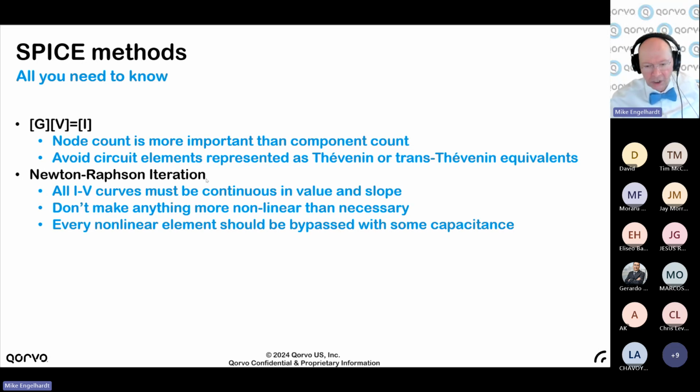It's closed for small perturbations, but at that point it is exact. So Newton iteration terminates in a numerical proof that has the answer. It proves that it solved the circuit. Now, if that condition isn't met, then it uses the solution of the approximation as the next point about which to expand the Taylor series and try again.